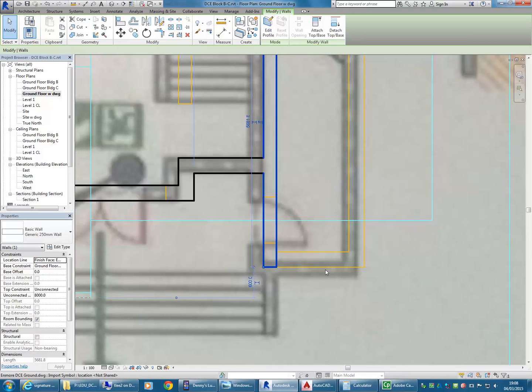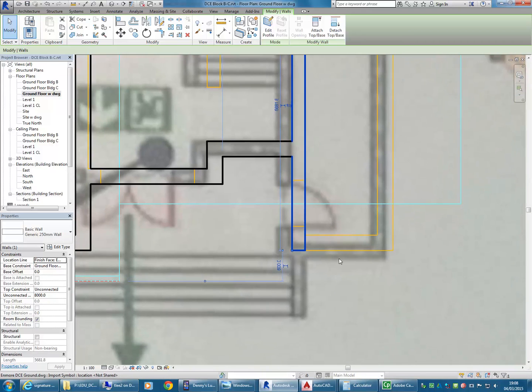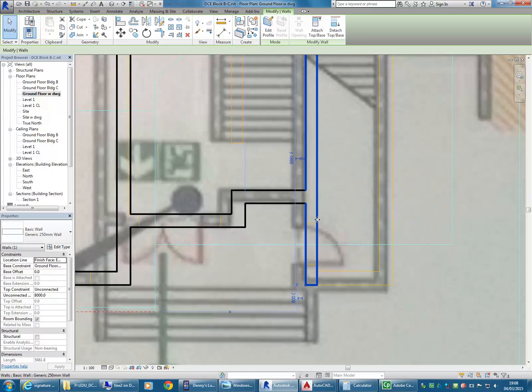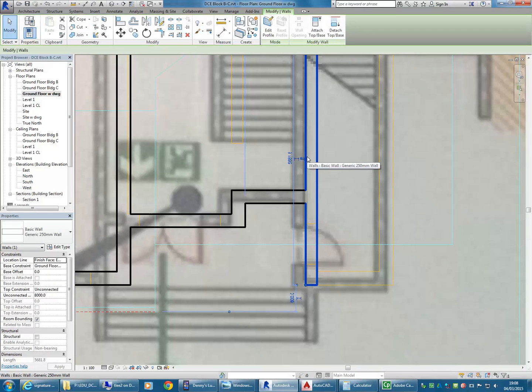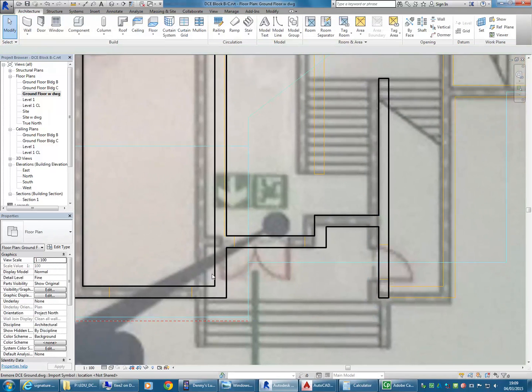There's a roof over this with a big eave that is enclosing all of that area, and it's just a storeroom. So you could probably assume that it's 250, even though it might not be. It's just a storeroom, so you could show it that way regardless, and that makes it much simpler, because then you don't have to have a different wall thickness for the inside part. So just rationalising the drawings and doing things like that can save you a bit of time.